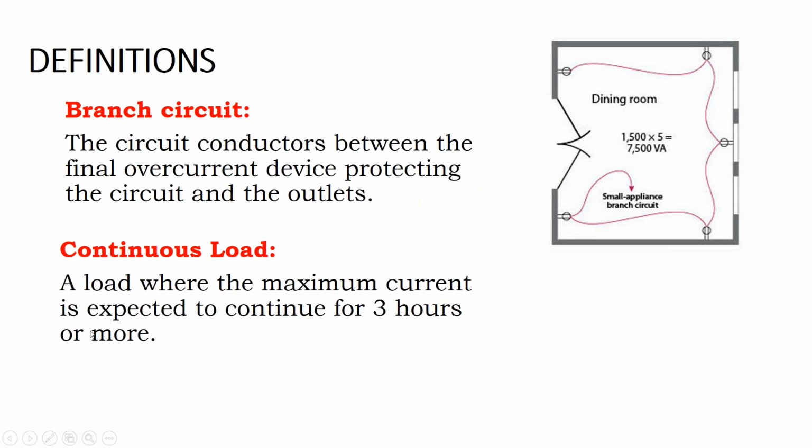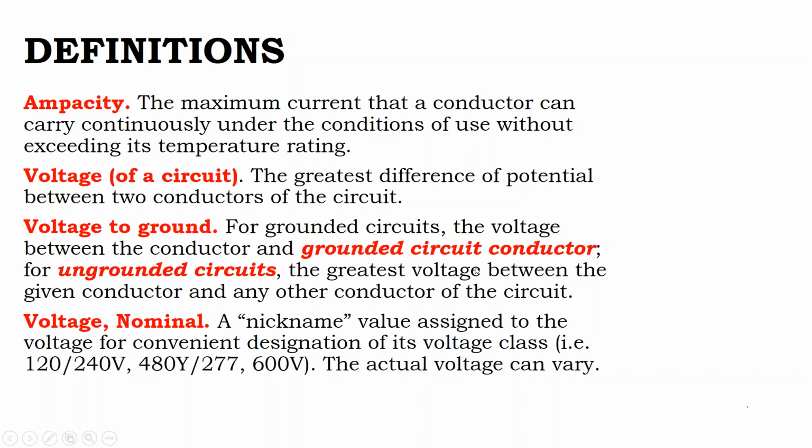And then we get to nominal voltage. And nominal voltage is kind of the nickname for voltage. We talk about 480 volts or 120 volts, and we see how you have a 120 volt circuit, but maybe your appliance is listed at 115 volts, and well, why is that? Well, that's because there's inefficiency in your cable, and by the time the 120 volt circuit makes it to your 115 volt appliance, it's lost some power. So that manufacturer thought that it would be smarter for them to say, no, it'll work at 115 volts, because they know that there's going to be voltage drop, and they want to assure you that their system will turn on if you plug it into a 120 volt circuit, and they're just overthinking things.